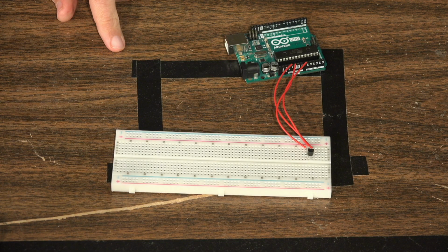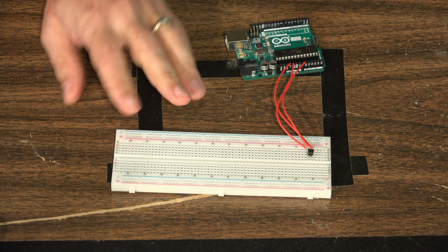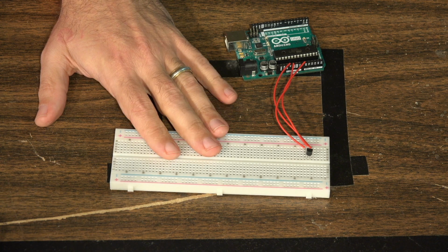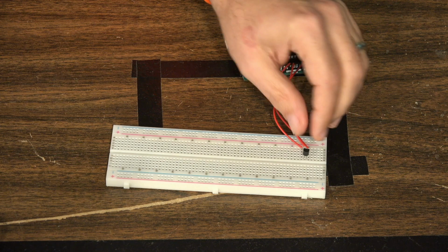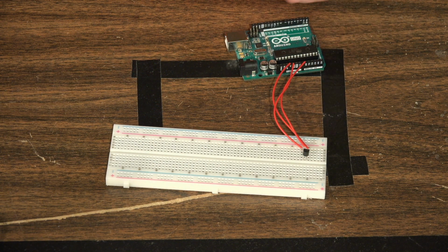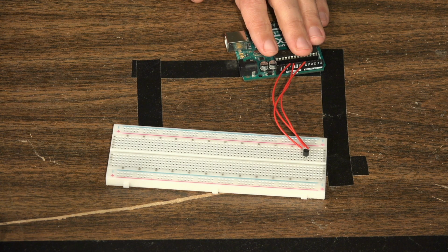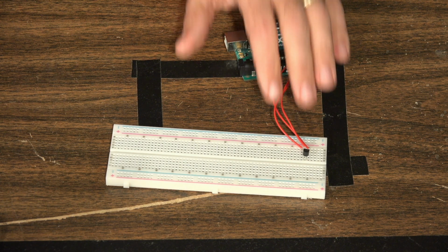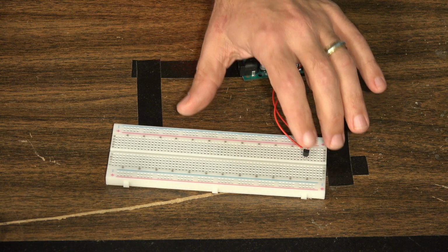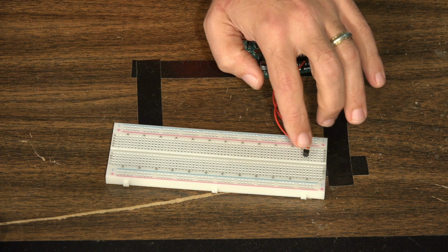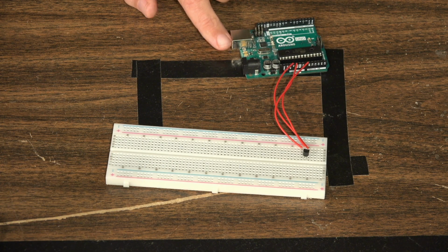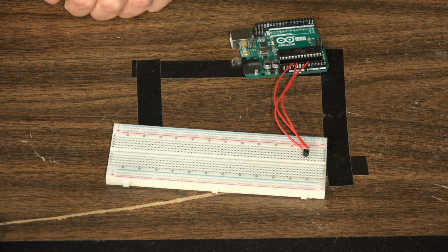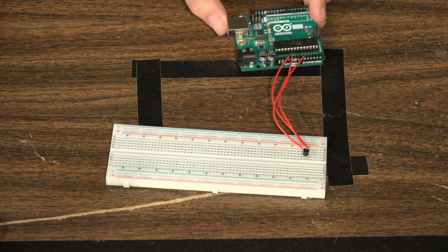So this is the physical build for this particular project. There's not a lot to it. It's the same standard thing I do for so many of these Arduino projects, where we're simply using the analog temperature sensor as a way of getting a dynamic input to the Arduino. We simply have our standard Arduino Uno here, though any Arduino board will work for this. This is connected to the analog temperature sensor. The output for the analog temperature sensor goes to A0, and then past that, I'm simply using a USB cable to connect to the Raspberry Pi, and that's all there is to it.